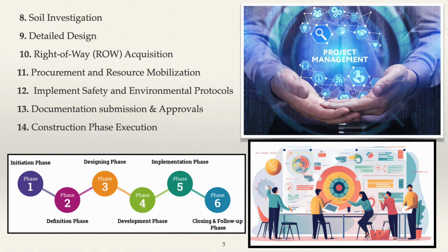8. Soil investigation. Its primary purpose is to assess the soil's characteristics and suitability to support transmission tower foundations. Soil sampling. Samples are collected at proposed tower locations, usually through boreholes drilled at various depths. These samples provide insight into soil composition, density, and moisture content. Geotechnical report. The results of the soil investigation are compiled into a geotechnical report, which outlines the soil characteristics at each tower location and provides foundation design recommendations based on the data.